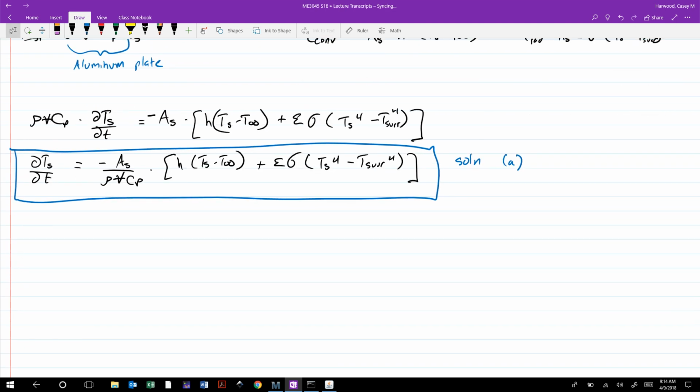Okay. So once again, it boils down to that convection. So for part B, we need h. I should mention here that h, notice that there's no subscript x and there's no bar over the top. Are we talking about a local convection coefficient, or are we talking about an average convection coefficient? Just based on, I heard an average. That's a good intuition, right? Why would that be?